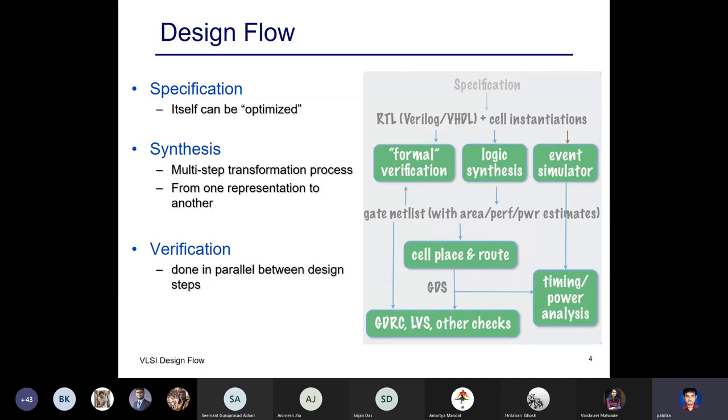But in addition, we can have synthesis steps here, where after this simulation we verify that the desired output is given, or even after synthesis, this verification is actually placed in many places in between. And then we verify things like whether the timing is correct, whether the power requirement is correct, whether the placement and routing do not violate the geometry that is permitted by the technology, CMOS or something. So after all this succeeds, you can come to the synthesis. So this verification happens everywhere in between. Okay, so as you can see, there are two steps.